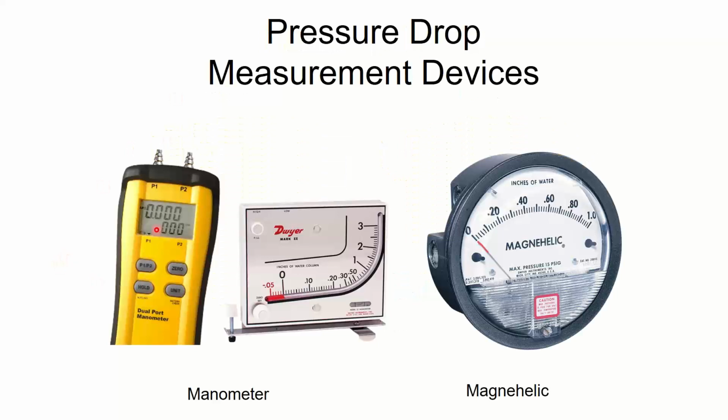The easiest way to do that is with a manometer to measure the pressure drop across it. If it's a large facility, the maintenance guys could probably measure them, get an idea of what they are, and then be like, okay, for air handler number 3, we pretty much need to do it every 4 months. But for air handler number 7, I can pretty much do it every 12 months, right? Just depends. Or instead of these fixed metering devices, you could put on something that ties to your building automation system and have it report back and tell you when to change your filter. If you have a BAS, it's extremely cheap and easy to add that on there, like tens of dollars. It's not that big of a deal. So might as well have the system tell you when it's time to change the filter.